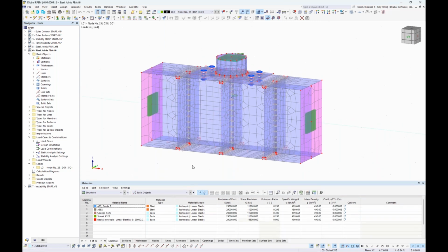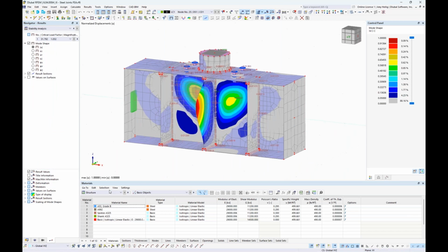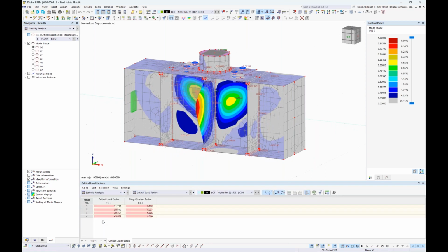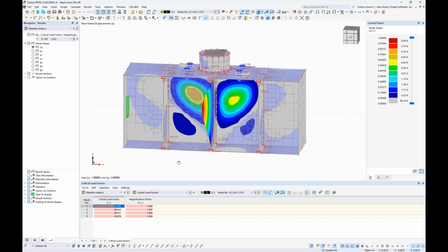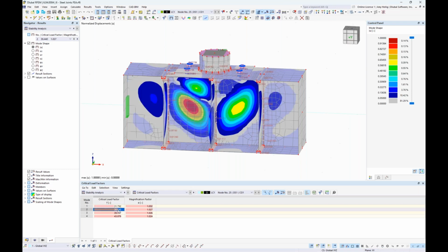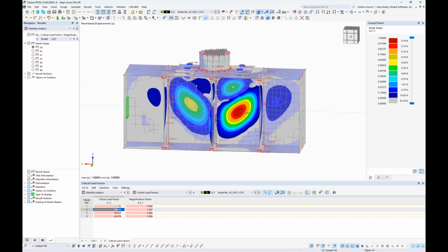And in addition to AISC design, again, we're carrying out the stability analysis. So every example that we've seen up until now is the same workflow that's going on underneath the hood, where we can view here under the stability analysis results 4 different eigenmodes, the critical load factor of 31.729 before we see kind of the buckling of that stiffener plate, and then also the relevant mode shapes here with slightly higher critical load factors.